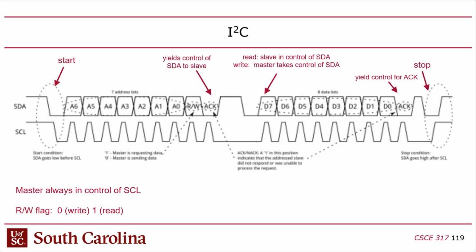Again, latches are just like flip-flops, but they're level sensitive. When the clock is high, it opens the gate and the data comes in; the clock goes low and it locks it off. It's like a river lock, the gates open and they close. So that's the idea with I2C. Now it has that weird start and stop condition, where the data actually does change when the clock is high. But that's only the start and the stop.